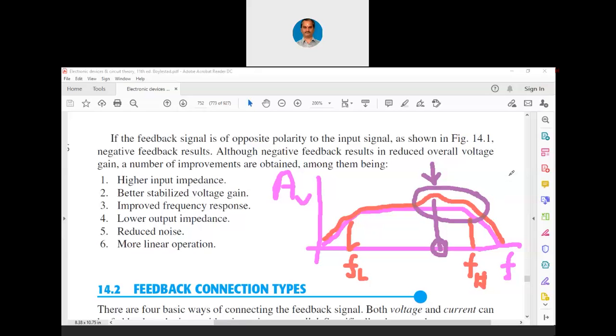So, at this particular point, wherever I am pointing, the gain has suddenly gone up, meaning the gain is increased. This increase in gain is due to the reduction in impedance at that time. The reduction in impedance may happen because resonance will happen within the circuit there. That resonance is again because of the parasitic elements there.